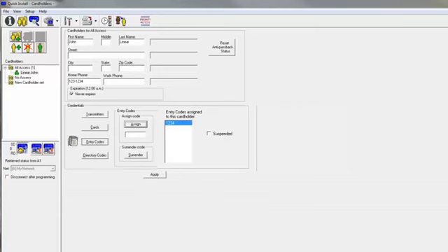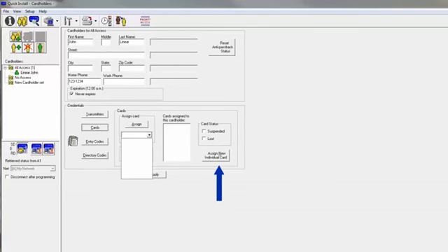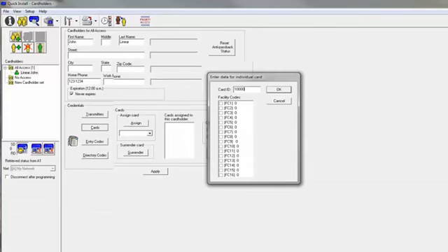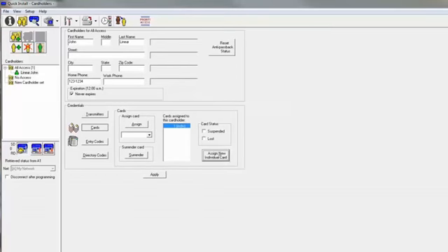A new option will appear to assign a new individual card. Select this option. On each card, there will be a number 1 to 5 digits in length. Type in the encoded number on the card ID, and select OK to assign it to John Linear. Once a new icon next to the card button appears, select Apply. The same process will apply if we need to add transmitters, directory codes, or a telephone entry unit.